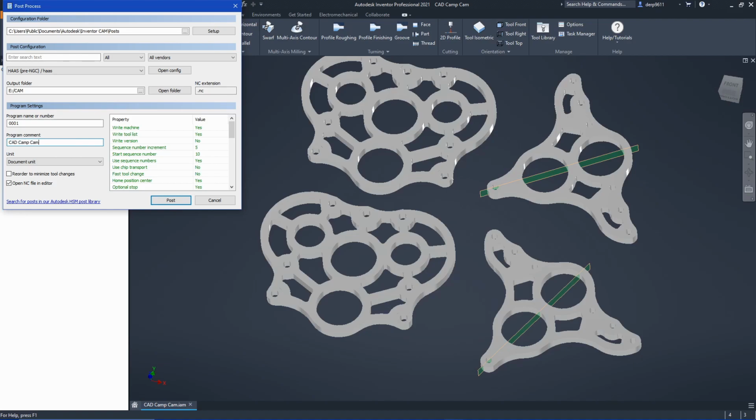Now in here, you're going to want to make sure that you select preload tool to no, because the mill type we have at Middleton does not have a tool preloader, and we're going to want to make sure that the built-in high feed rate is at maximum 400. Finally, we can click post.